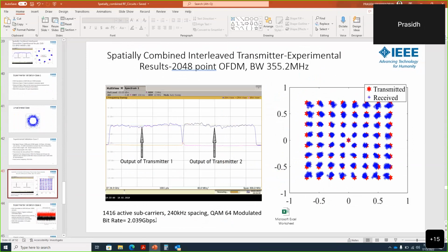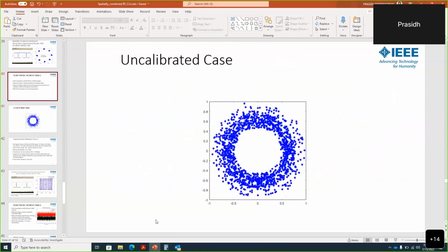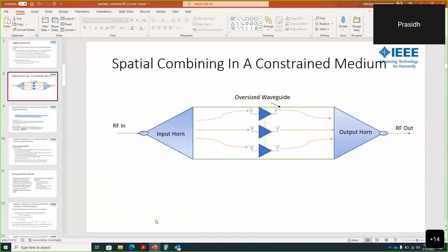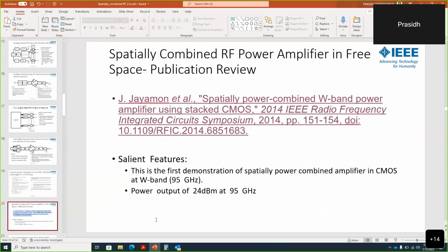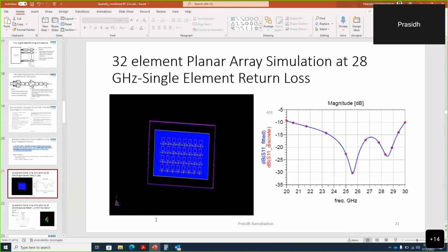Okay, but if I compare it with the time interleaving case, is that pretty much comparable with what you would get with a time interleaved system? Well, it should be slightly better, in my opinion, because in a time interleaved case, the mechanism that you have to correct for clock skews between the interleaved stages is quite minimized.